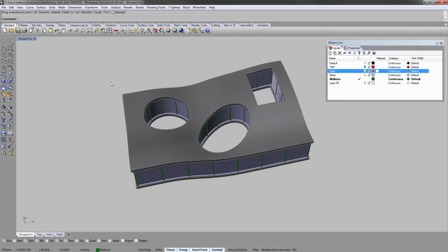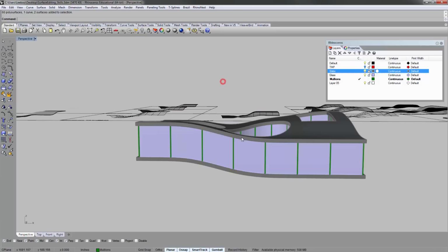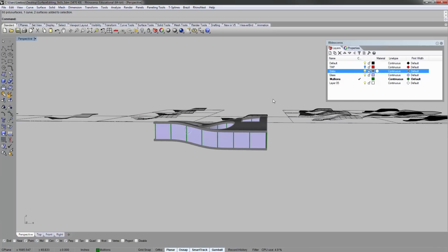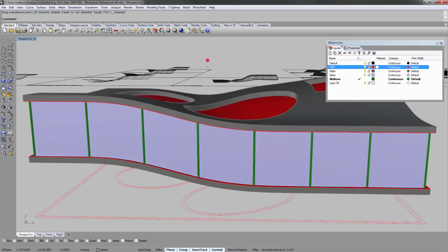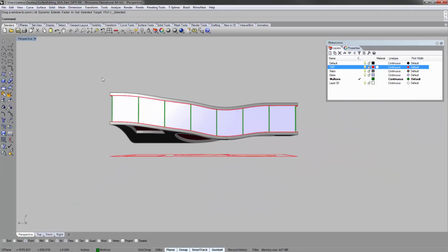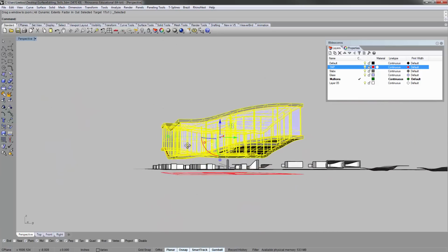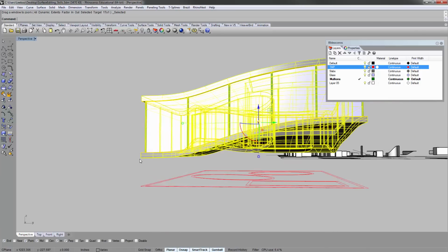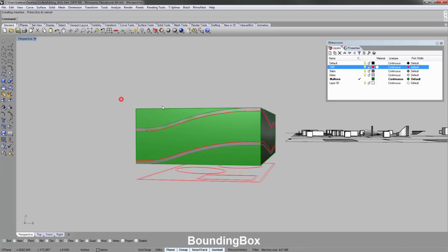And you can maybe move this back so it's sitting on the ground. I lifted it up so it's easier to model and look at the stuff that's below, but you can easily do that. And remember, when you're not sure what the lowest point is, at least in this case it seems like the lowest point is here, but if you're not sure what the lowest point for whatever geometry you're trying to do is, you can always run the bounding box command, enter.